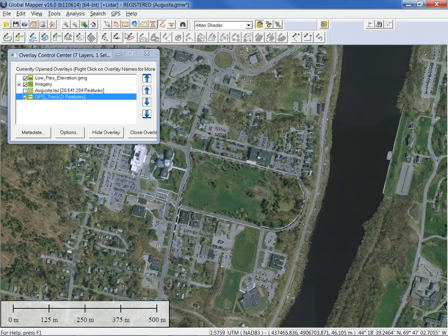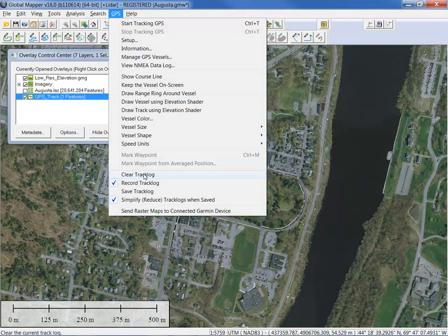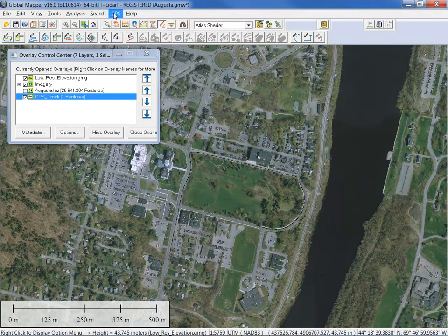Absolutely. Obviously, we're dealing with points here, so for any point feature that's generated in Global Mapper, there are multiple export options that would be compatible with the device. GPX is the one that's most common, but simple XYZ or text files would also be compatible with some receivers. So absolutely, by way of preparing for your work in the field, if you're using a standard handheld GPS receiver, absolutely Global Mapper can be used to create those waypoints. So that is certainly part and parcel of the way we work with GPS. I just hit the clear tracklog button to get rid of that tracklog, by the way.